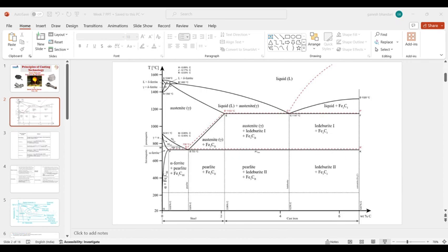Okay. So coming to the quenching process. When we are going to quench it down, we have to miss this nose part. What do we call this part? We call this part the nose. So we are not giving enough time, or a low enough cooling rate, for the conversion of austenite to the pearlite phase. So when we are going with the quenching process, we are not crossing this line, the start point at which stable austenite is going to get converted into your pearlite phase.